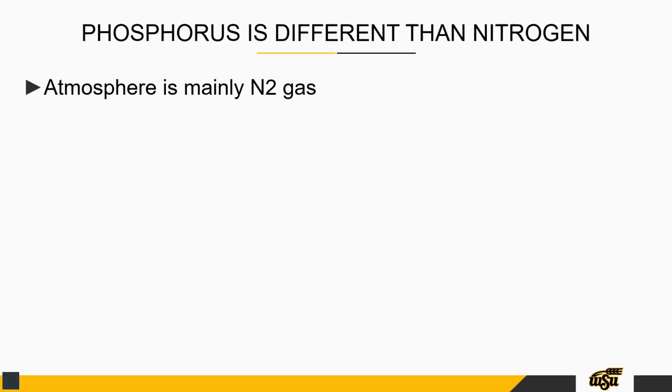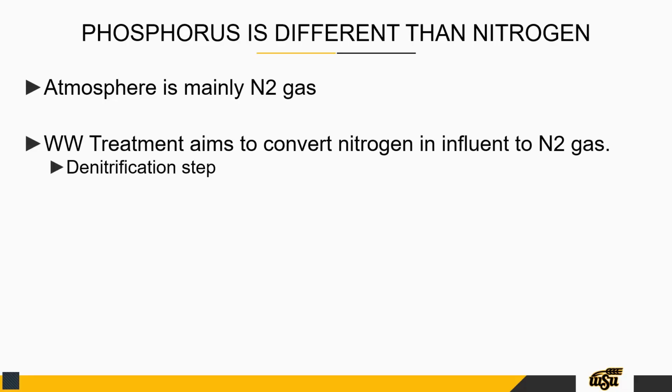Another takeaway here is phosphorus is different than nitrogen. You convert your ammonia into nitrates and then you denitrify and then you get into gas. That denitrification step is not something that there's a comparable step with phosphorus. You get rid of nitrogen in your plant and it stays out of solution because it is actually gone from the liquid and solid streams.